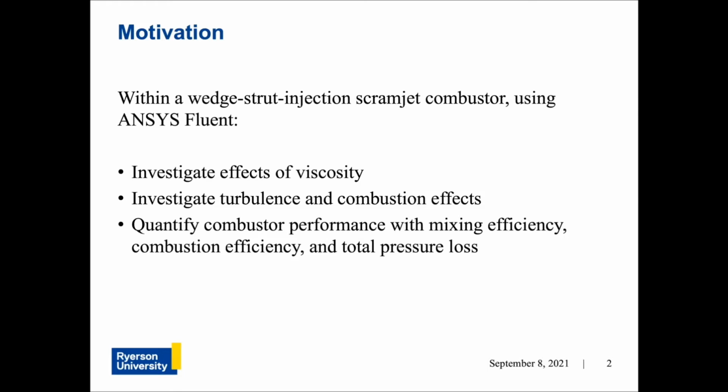With the effects of viscosity implemented in the model, boundary layers should form along solid walls, and a free shear layer, or mixing layer, should also form around a hydrogen injection stream due to the difference in velocity from the bulk flow to the hydrogen stream. This causes friction between the fluid layers and between the fluid layers and solid boundaries.